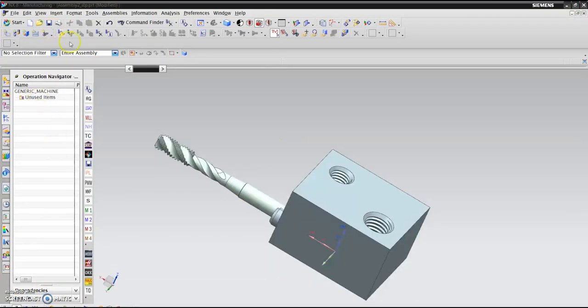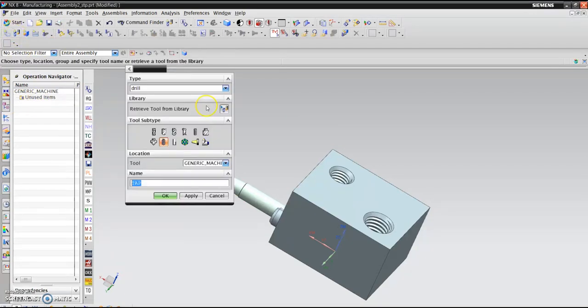Let's start selecting the tooling that we need to create the tool path. We said that we need a drill. The drill needs to be the size of what we did the math on. We know that we have two different threads, M8 by 1.25 and M10 by 1.25. Based on the math that we said, we subtract the pitch from the major, and it will give us the drill size that we need. There's a drill chart. You can use that too. That'll be easier.